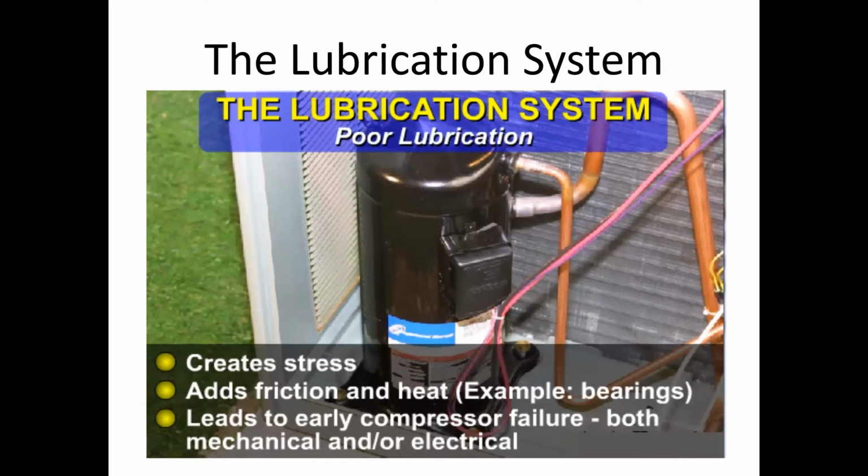It is the same system that we're moving refrigerant through. But those refrigerant lines, that line set, is doing two things, right? It's carrying the refrigerant that we use to absorb and reject heat, but it's also carrying the lubricant that helps the internal mechanism of that compressor move freely, right? Just like you can't drive your car or your truck for very long with no oil in it. The same thing happens with your compressor.